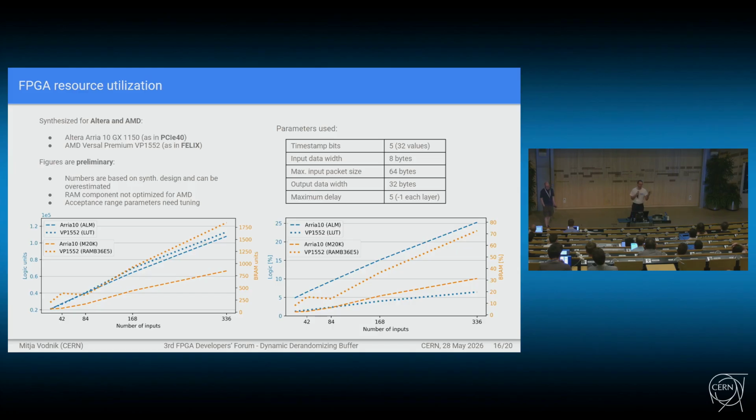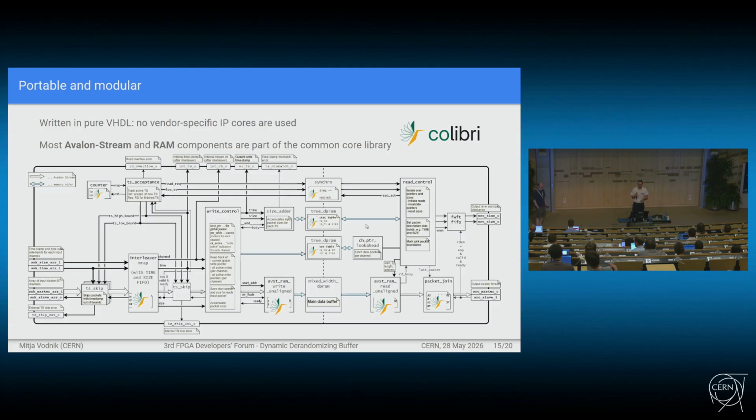Perhaps, as I said, it's not optimized for AMD. UltraRAM is on AMD, right? It's not in Arria 10, yeah. So for now, I'm targeting Arria 10, and I'm OK with RAM there. For AMD, as I said, there's this component, the mixed-width dual-port RAM with byte-enable writing and reading, which is not really supported. So I need to simplify that a little bit, and then I will see. If I need to use a different RAM, then...